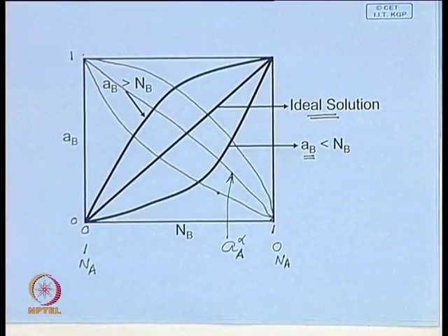Now, this situation, when does it happen? In a solid solution consisting of two metals A and B, if they are mixed at random, everywhere you go the atom fraction of A equals the fraction among the nearest neighbors. Suppose the crystal structure is FCC, you have 12 nearest neighbors.